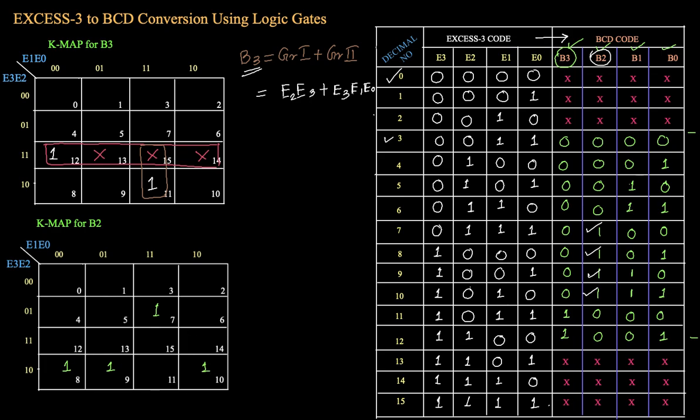Now, to make the Karnaugh map convenient, we can take two don't cares over here to make a group of 4. And obviously if we take another don't care, then these 4 corners make another group. Also, if we take one don't care over here, then we get the 4 group.